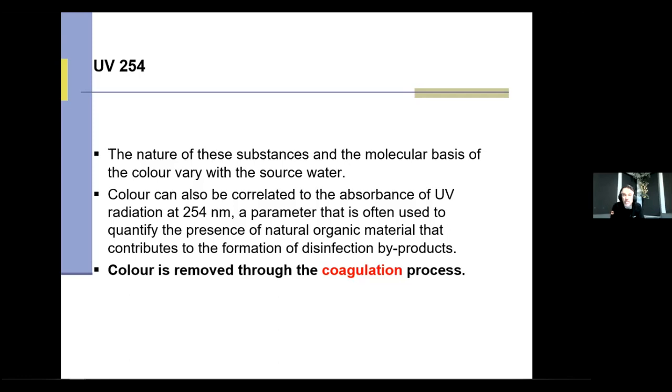Now we talked about these colloids, which are color and organics, right? And now let's get rid of this stuff. The note before we go on is that those disinfection byproducts that we talked about in the disinfection chapter of the course, really color and organics mixed with chlorine causes these disinfection byproducts. And remember, those are trihalomethanes or those haloacetic acids. So the more color and organics that we don't remove before we chlorinate, this can cause disinfection byproducts.